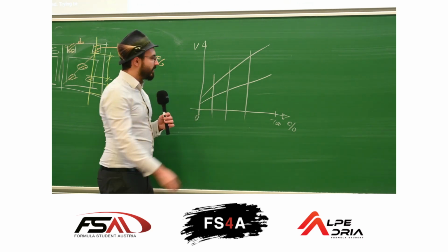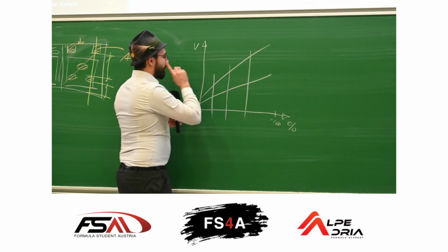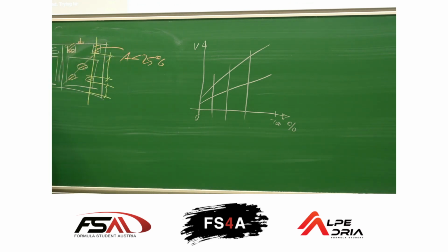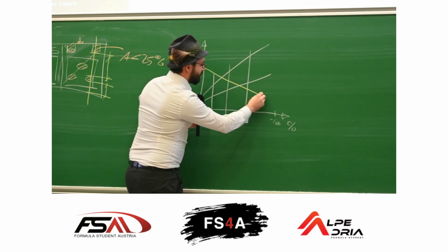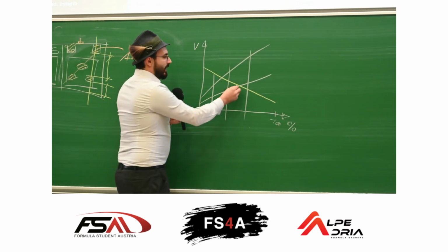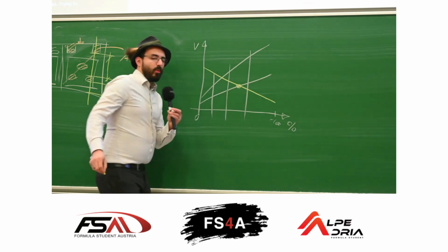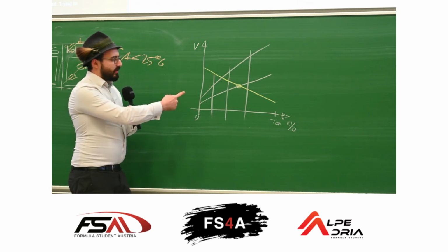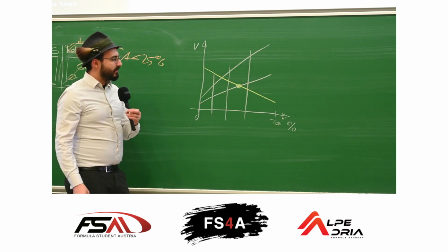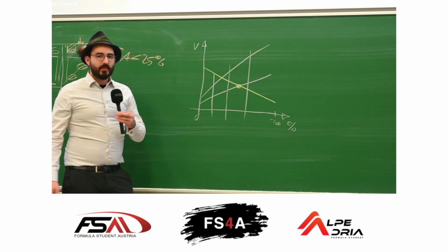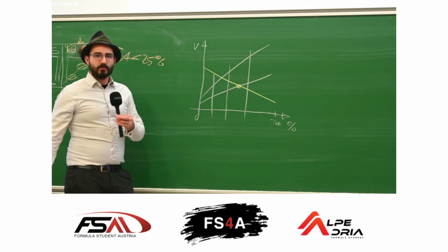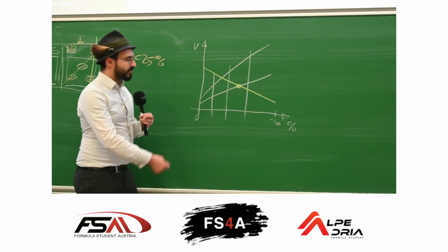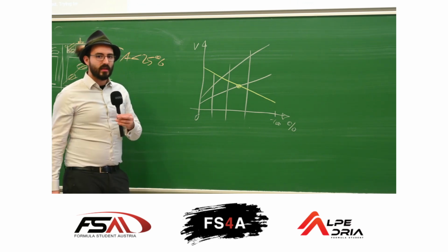The other thing would be, like you are proposing, that the second signal is like here in green, then you have one point where both signal outputs are exactly the same, and the system cannot tell if actually both signals are still working or there is a shortcut between the signals and both signals are the same because of the shortcut.